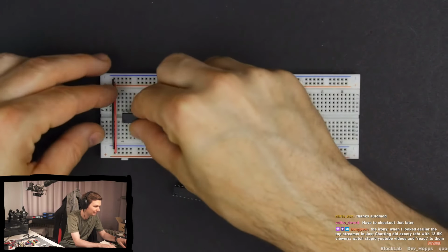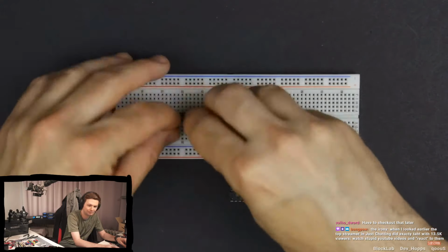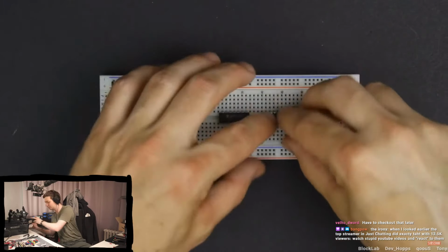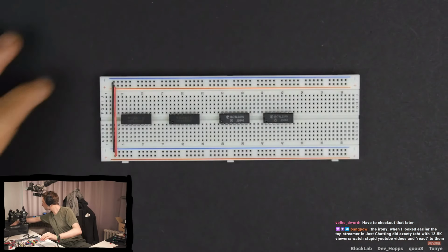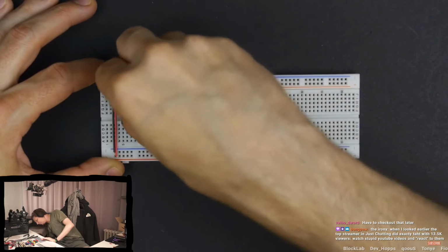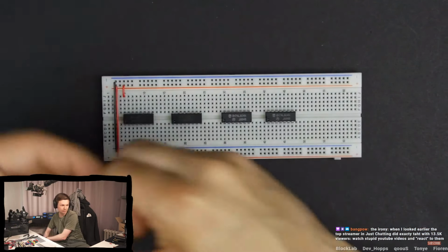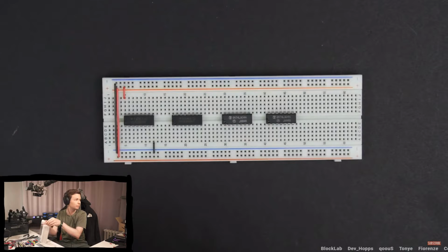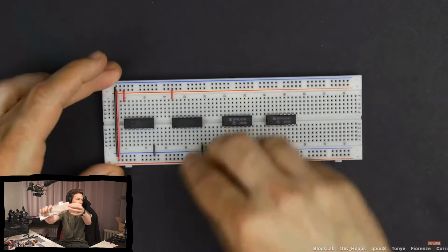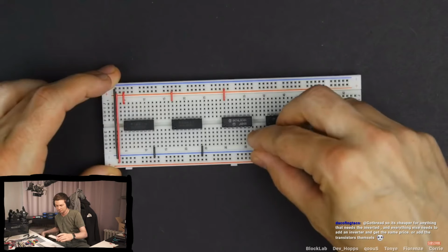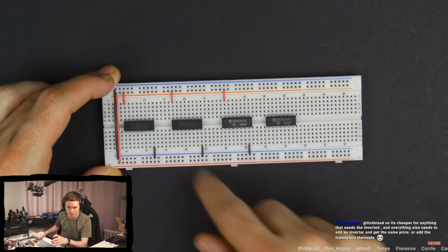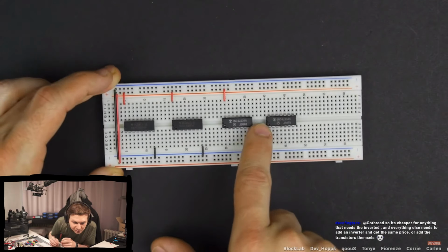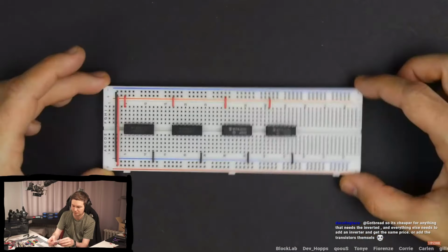We'll start out by sticking these things on the board here. So we've got our 2 74 LS189s and our 2 74 LS04 inverters. So now I'll just hook up power to each of these. The last pin here is the 5-volt power, and pin 8 or pin 7 on these chips is ground. It's pin 7 on these chips because these are 14-pin chips instead of 16-pin chips. Pin 1 is over here on the left. See the little dot there indicates pin 1. So we got the power hooked up for all of them.